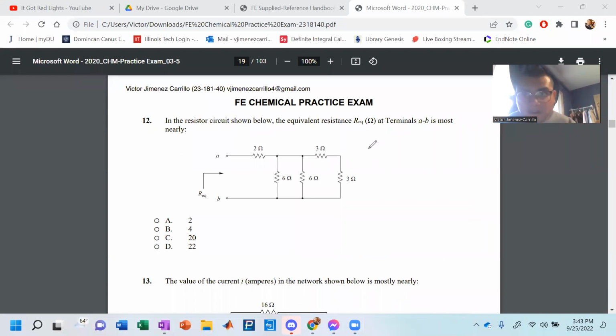Resistors in series, resistors in parallel. If we're going to do this, resistors in series are simple. They just add up, they just add the equivalent resistance. Resistors in parallel are R equals 1 divided by 1/R plus 1/R. I hate this. Here, 1/R, etc. Those are resistors in parallel. Resistors in series are just a simple R plus R, which is nice. Now, with those basics out of the way, these two are in series, so they add up, and you get to rewrite this.